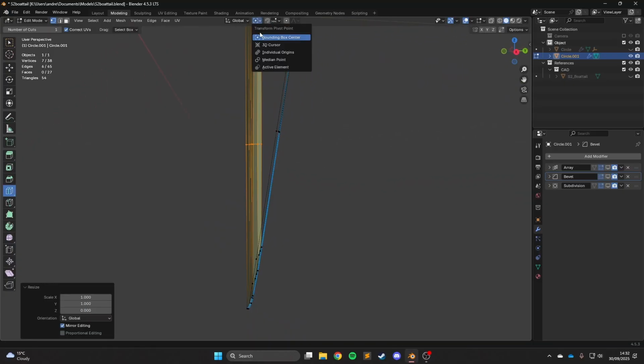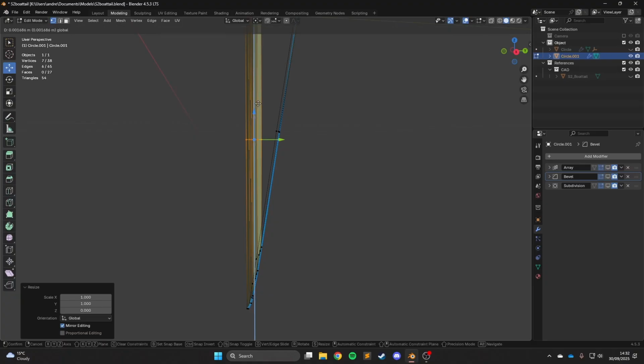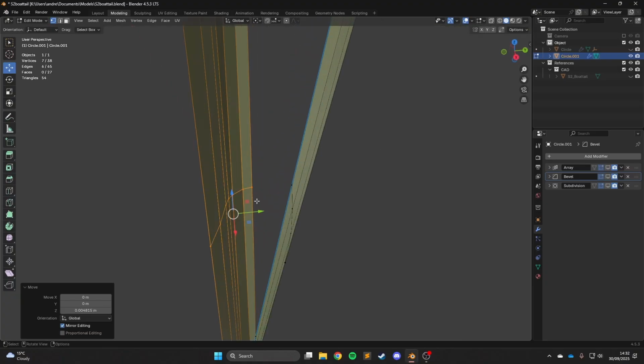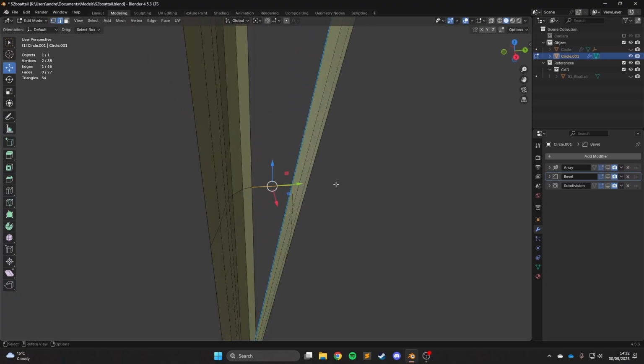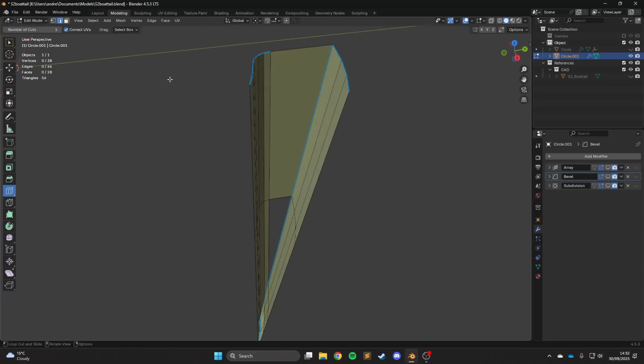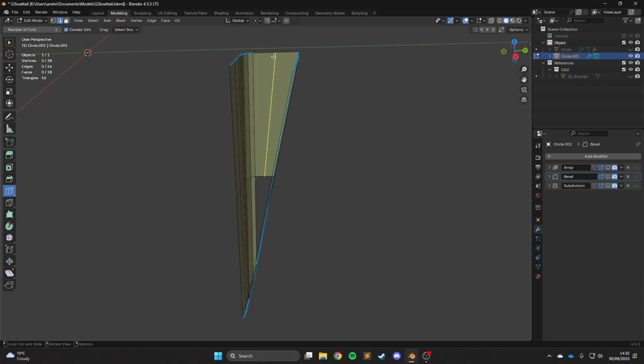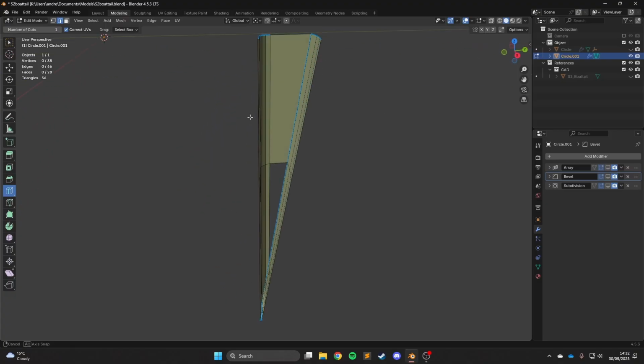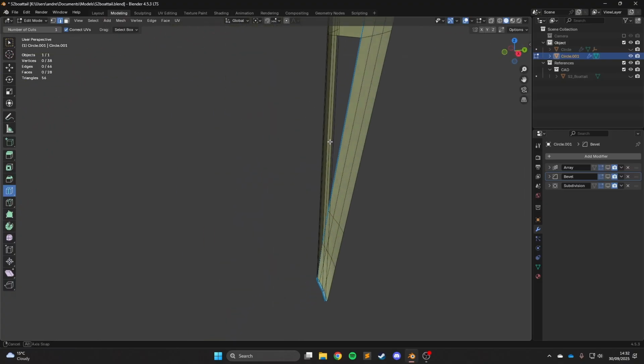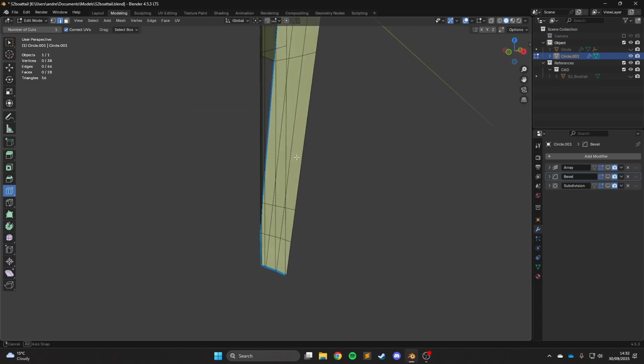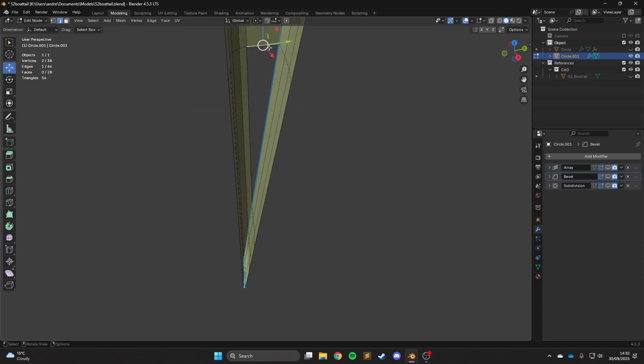So, and just, if there's any dodgy geometry or any dodgy kind of tool paths, it'll be confined into this hole, essentially. So instead of, if I wanted to make a cut and it went in here, it would go all the way back and up and all that. If I make a cut in here, it's predictable and it kind of mirrors across. If there's any screwed up geometry, it's confined to the one place and it kind of doesn't affect the rest of the model.